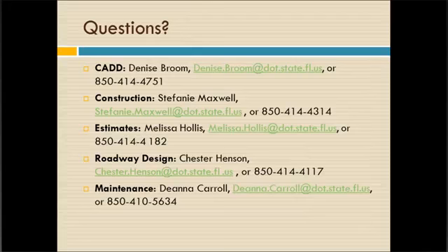Notice if you're dealing with refurbishment markings, you'll notice that a lot of times the flow chart says you need to talk to the district maintenance engineer to find out how long the service life of that pavement is and how long those markings need to last. And the district maintenance engineers will make those calls as to whether they want to put down spray thermo or refurbishment thermo, or whether they want to use durable paint.